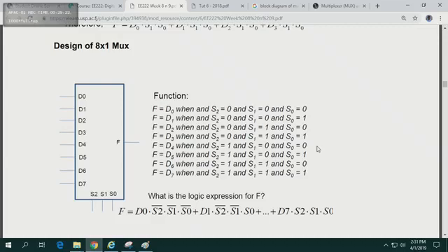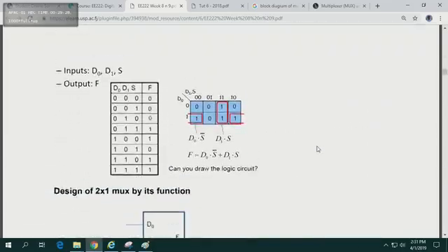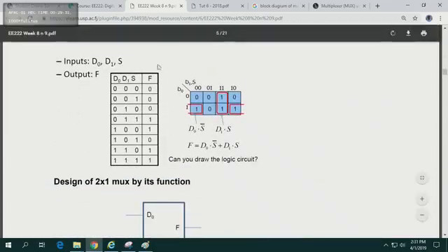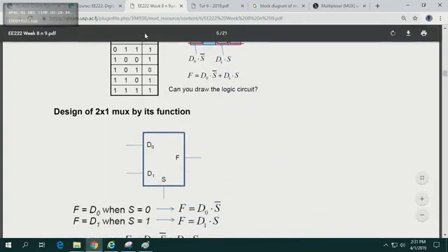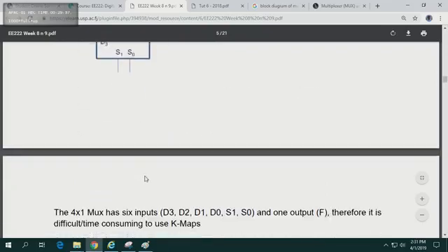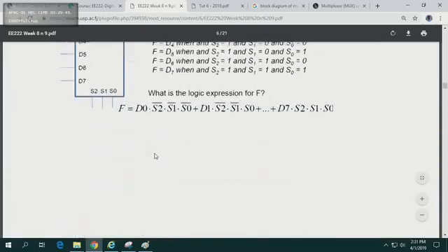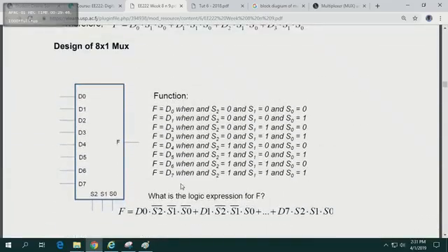And how did we come up with this method? We saw the pattern over here when we did the 2:1. When you do the 2:1, it was easy because only 3 inputs, 8 lines, right? We saw that A, and then we were able to pick up what's happening here. So it's only that particular line will go on when that particular input is selecting it. Okay, so then we learn from this. All right, so that's our function for our particular 8:1.